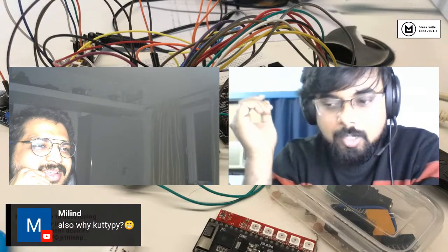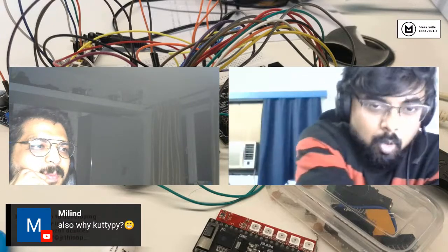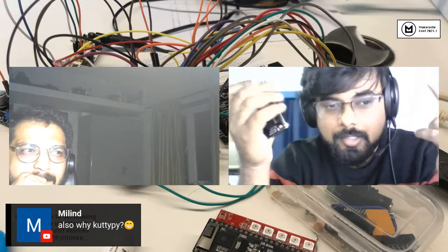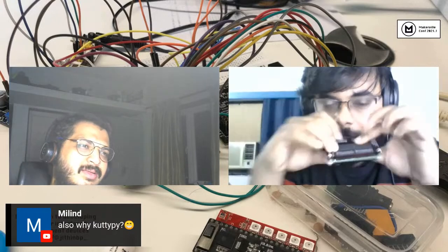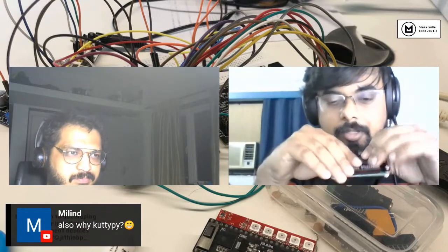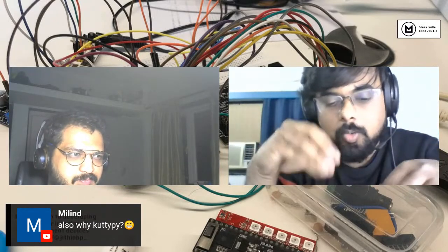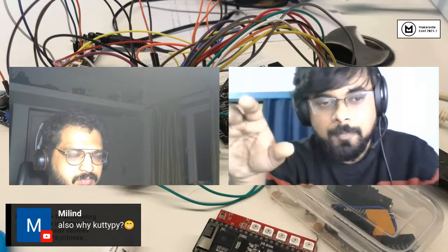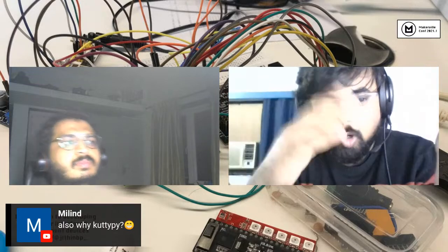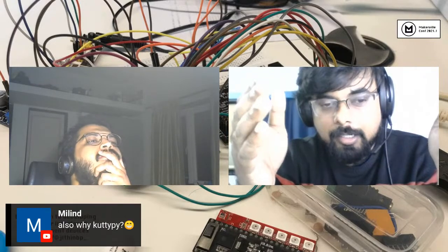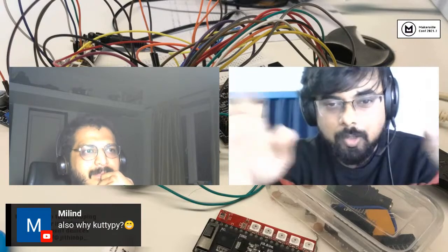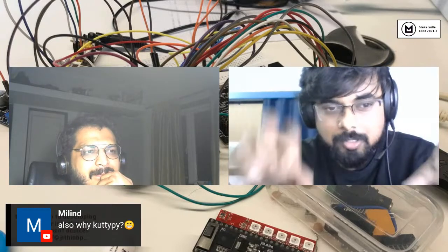At the time, what he had was this board with a Python library with two functions, set register and get register. And there was a firmware, like a normal firmware. The bootloader was not involved. There is a firmware whose job is to read and write registers. So now you can use Python command lines to just toggle registers. Then I started playing with this and I figured, why not make a UI for it? Then I had a real-time UI where you can visualize the entire input sets, output sets, toggle, play around.